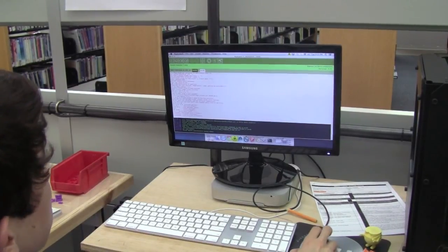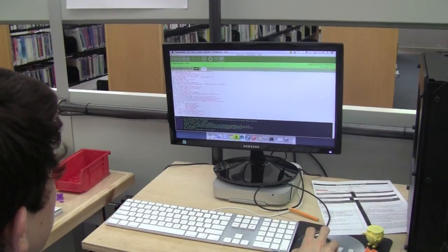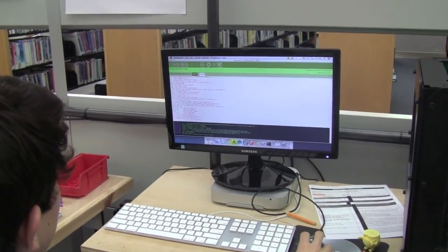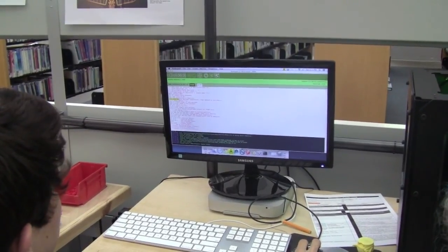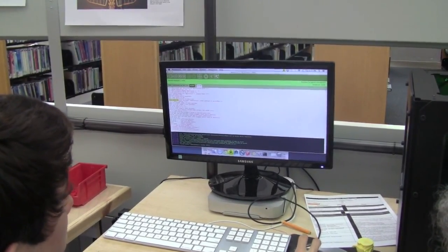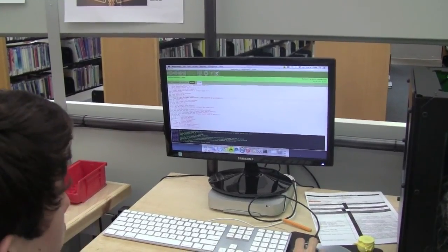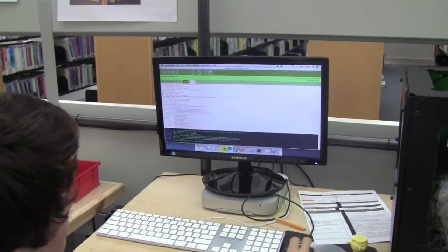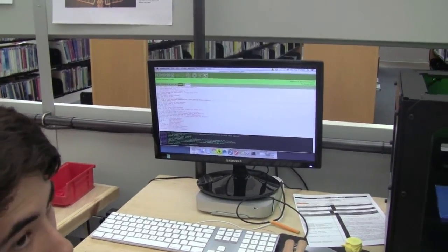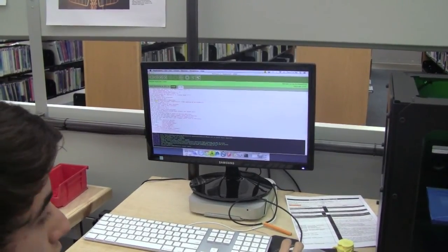You can see at the beginning, it's just commands. Where is it? Here you go. This just says set the extruder temperature to 220. So you can actually modify the G-code directly if you want the temperatures to be different. I've done this in the past when people accidentally set the print temperature to 180, which didn't actually melt the plastic. You can go in there and fix it. Instead of regenerating, you can just edit the G-code and change the temperature that way.